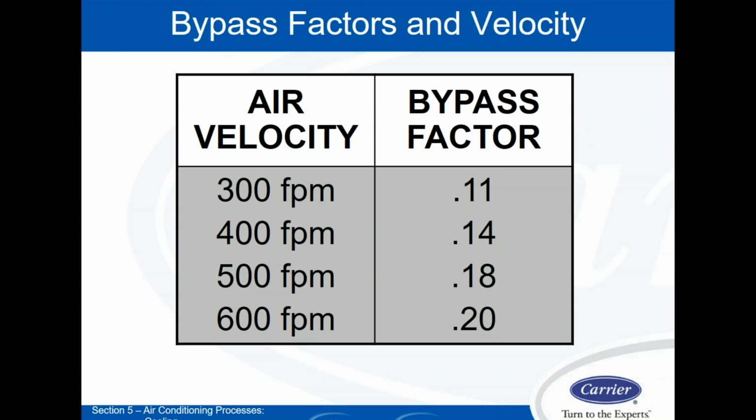So sometimes, for dehumidification purposes, we will intentionally slow the airflow down on the air handler to do a better job dehumidifying for that particular moment. So if I have a variable speed drive on my commercial air handler, or I have a variable speed fan on my residential furnace tied to my cooling coil, I can slow those down when I'm in a dehumidification mode specifically and get a better dehumidification rate, which means I'm going to have a lower bypass factor, which means I'm going to have a lower sensible heat ratio as well.